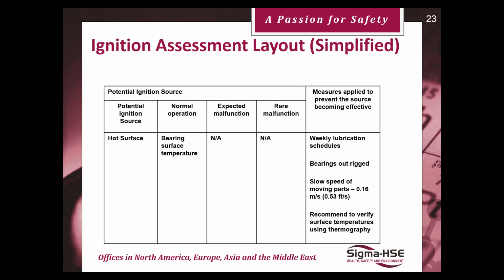So even in the standards, the 80079 standard, it gives you the steps to undertake to have a safeguard against a certain ignition source. For example, you could do load testing on your hot surfaces, so you can actually prove that when the equipment is run at load, or say 110% load at certain time intervals, as evidence, and then you can show that this temperature never goes above or close to the ignition temperatures with a safety factor. So that's why I guess it recommends to verify surface temperature.